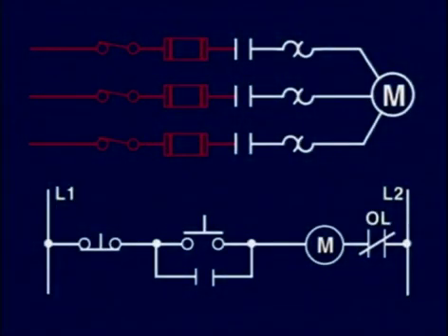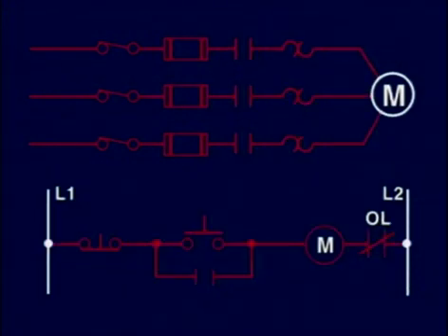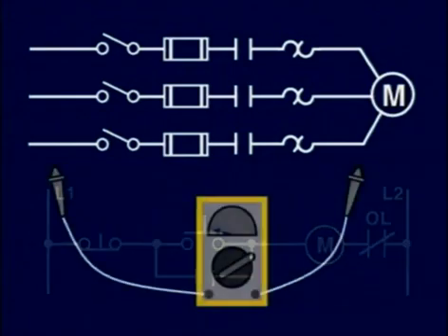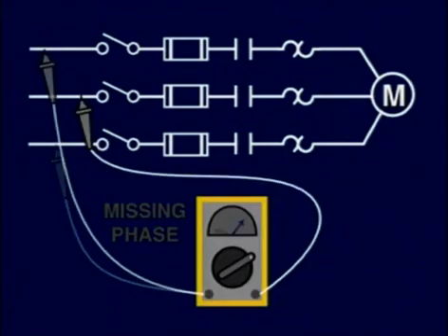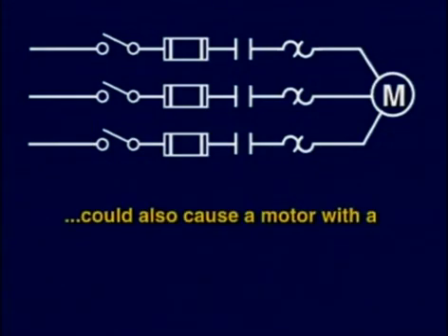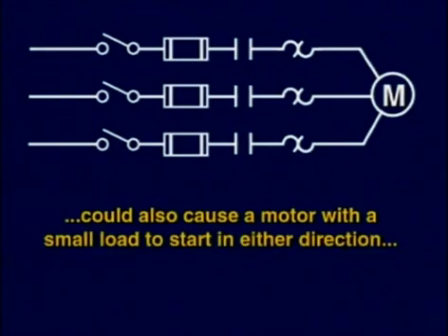If the single phasing occurs with the motor at rest, then it will most likely not start with the load, and it will give a hum sound if it is started. If an electrician or technician assumes that the motor is bad and changes it, the same will happen to the new one. We must check the incoming voltages for a missing phase. A single phasing condition at rest could also cause a three-phase motor with a small load to start in either direction, which could cause damage to other equipment.